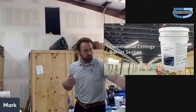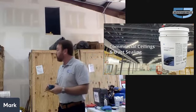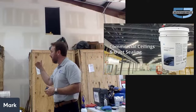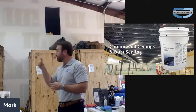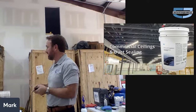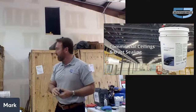We also see this as a rising need, and that is commercial ceilings, where we need to meet that black specification, but have a moisture and mold resistant system in the ceiling versus just plain paint, right? So when you're up high, heat rises. Condensation issues are created, especially because, again, you've got ductwork. Air conditioning is running through that steel ductwork, creating condensation, hot air and cool air converge, moisture content rises, things like that. Okay, so it's just all pragmatic stuff centering on dew point, right? But we have to know where all of those areas are that are problem areas.